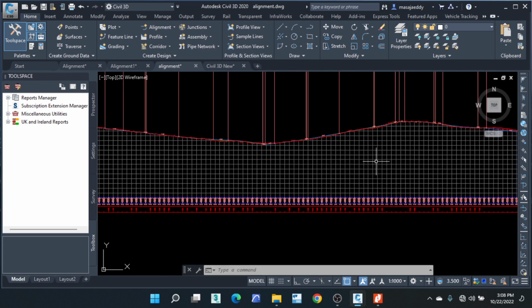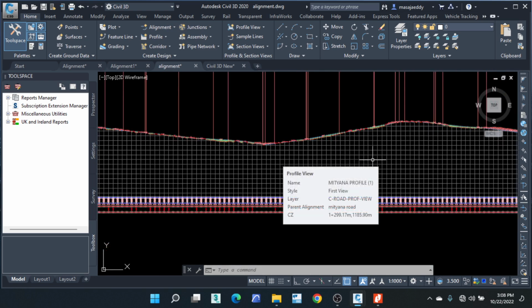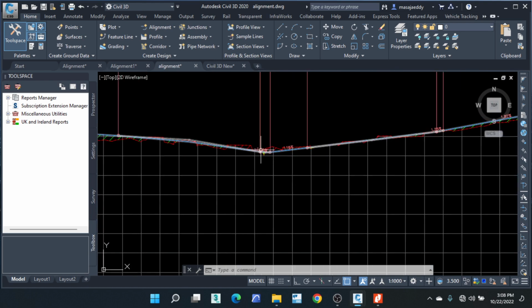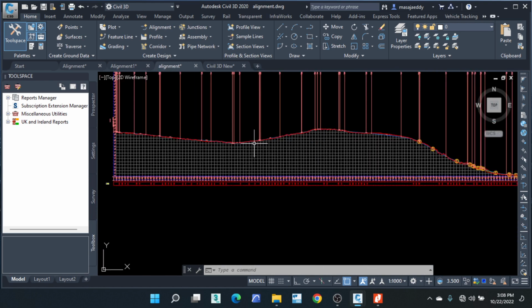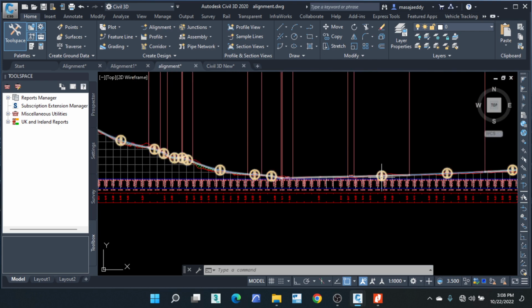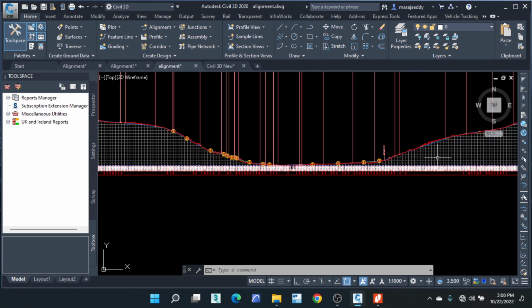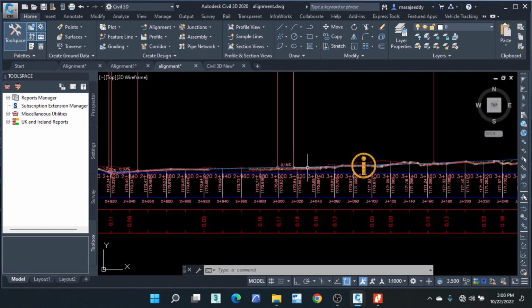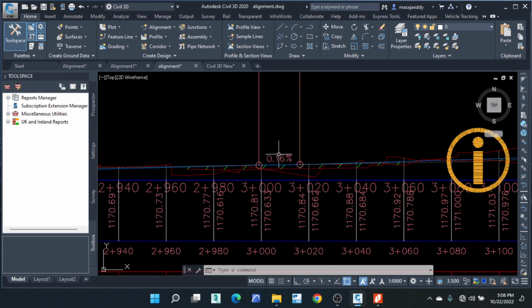Then also we are going to assume some points have culverts. So we shall add some fill at those points. For example, this is a swamp here. On ground they constructed some box culverts at this point here. It floods during the rainy season, so we have to add some fill here for drainage.